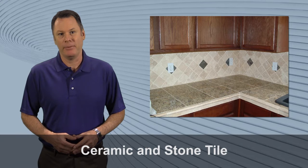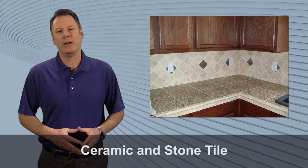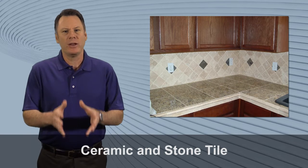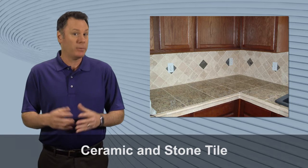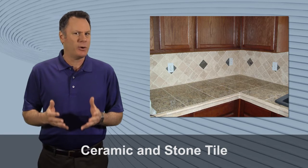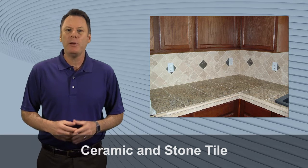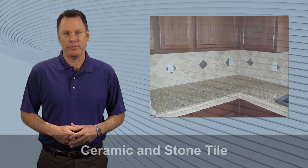Ceramic and stone tile. Although ceramic and stone tile have great design flexibility and are extremely resistant to heat, these types of surfaces can trap dirt, bacteria, and mold in open seams and grout lines. In addition, the grout can crack easily, allowing moisture to penetrate and giving bacteria and mold a place to grow. Consequently, the grout must be properly maintained and cleaned for hygienic and aesthetic purposes.